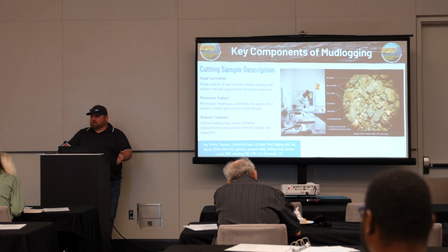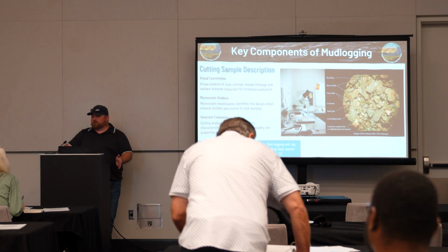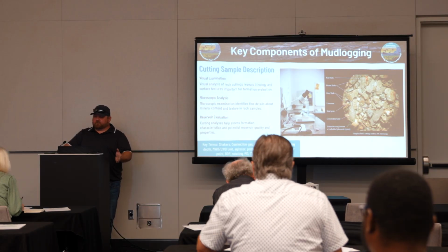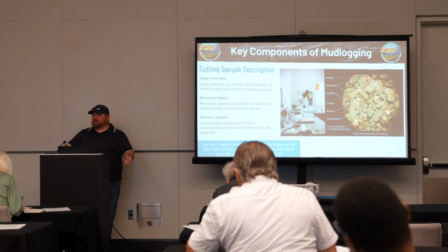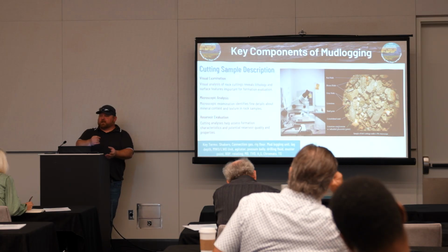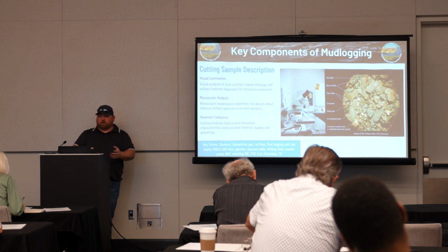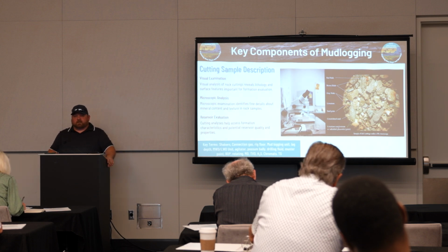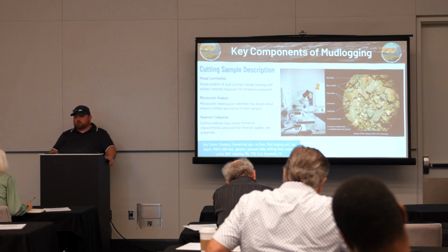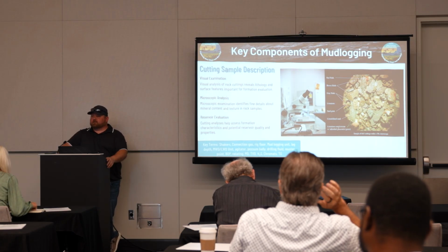A lot of people do it differently. Most rigs have a hose at the end of the shakers, because they use the hose to wash off the shaker screens and make sure there are no holes in them. If there's a hose there, it's a minute or less to wash a sample. You can spray the hose in there with light pressure while it's vibrating on the shaker, and it'll vibrate the mud off real quick, oil base or not. That helps in drying it as well. So you're at 4 or 5 minutes there, and then 2 or 3 minutes back to the trailer.